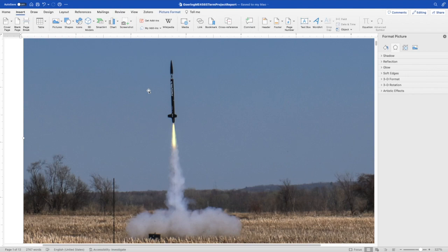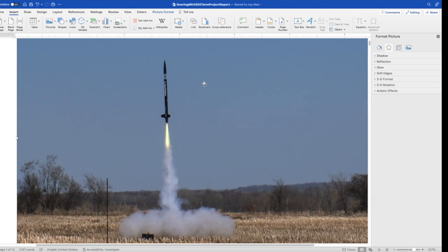So in order to optimize the stability of this rocket, for this project, I looked at different fin lengths, or fin heights, so that the distance from the edge of the rocket to the tip of the fin, and I wanted to see how big can you make the fin without causing the rocket to oscillate in an unstable manner. And in order to figure that out, I needed to run a bunch of simulations to assemble tables of coefficients of lift, drag, and moment versus angle of attack. So I'm going to walk through how to put together those simulations now.